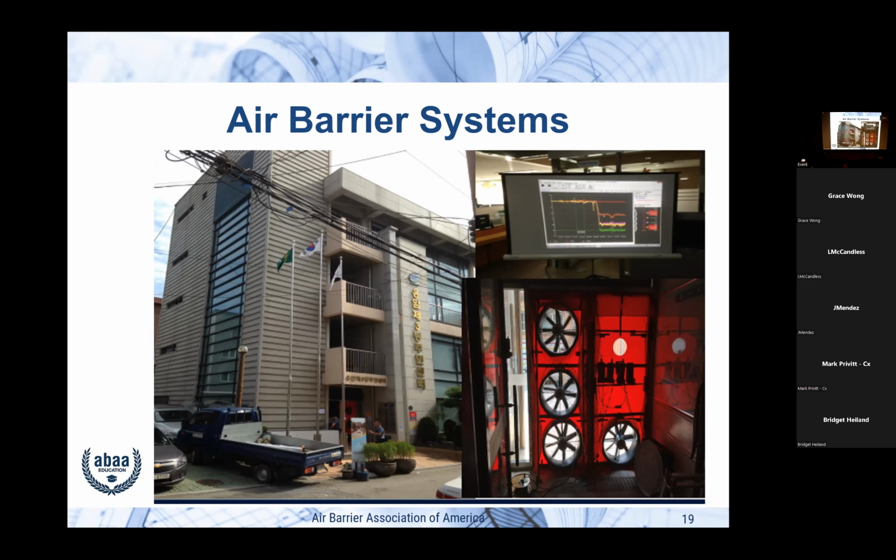And I'm not joking, you guys could all run the test because it's going to the computer and pressing enter. The manufacturers of blower doors have done a tremendous job of automating these things and doing the report. It even spits out the report for you. But it's preparing the building. And that's why the new standard E3158 is so important, because it gets into the details of why and how you do the building.